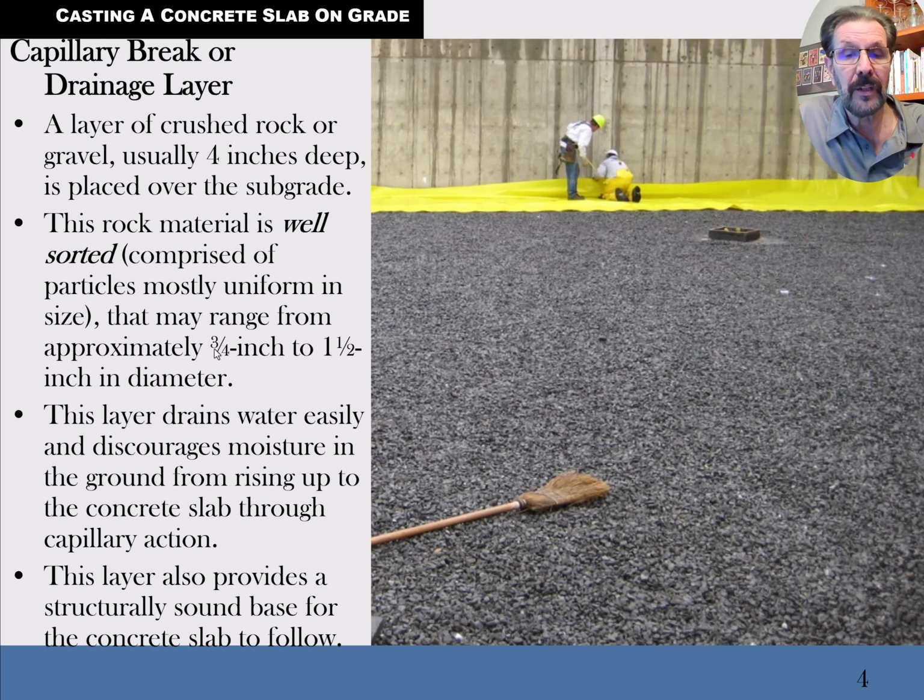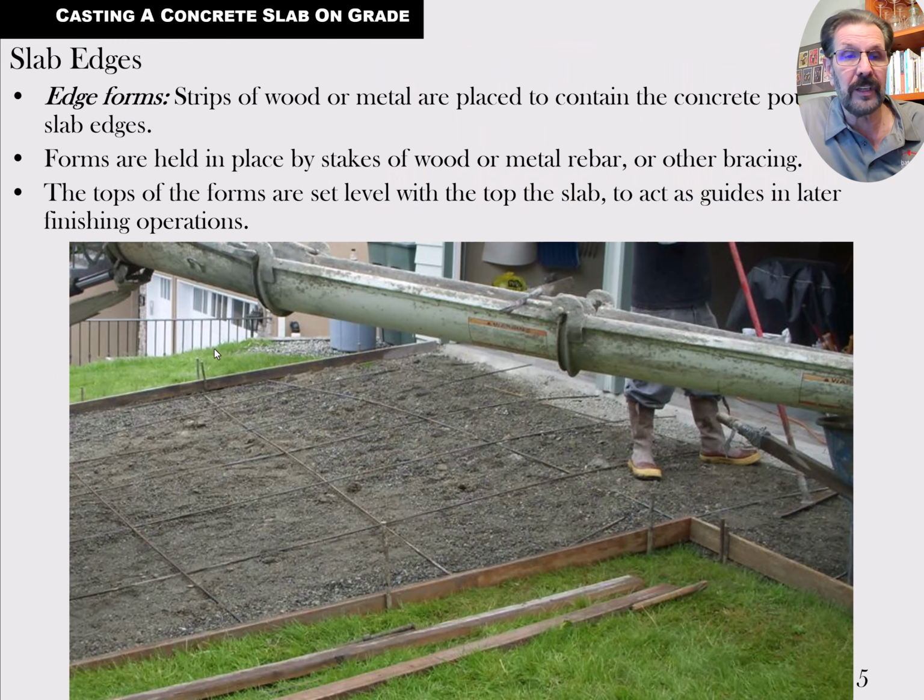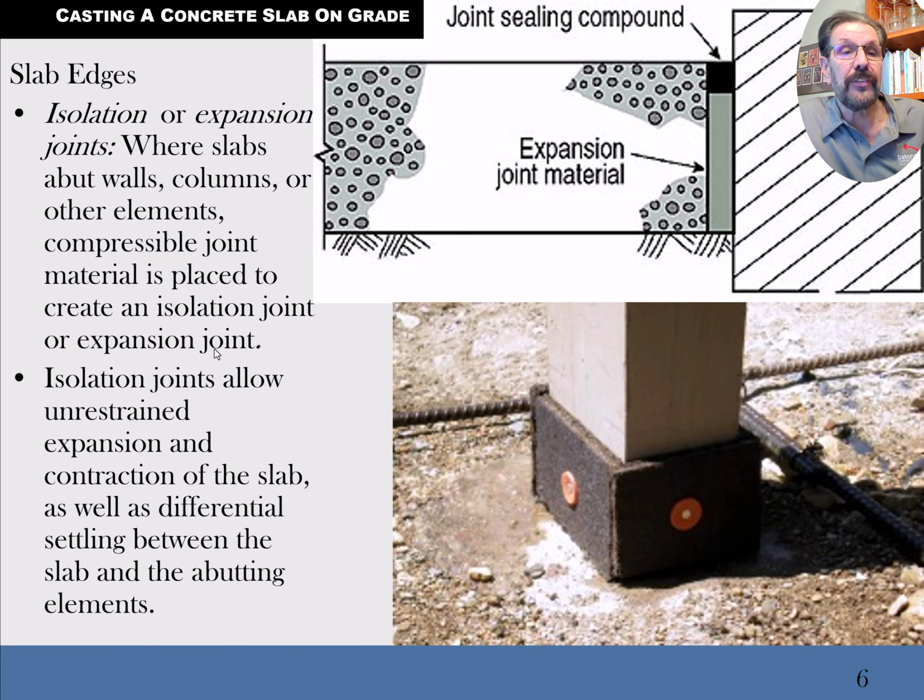It's not really structural in that it's not supporting vertical loads, but it is generally structural in that it's pinning the bottom of that basement wall to keep it from kicking in from the load of the dirt behind it if it's backfilled against. Okay, more detail.